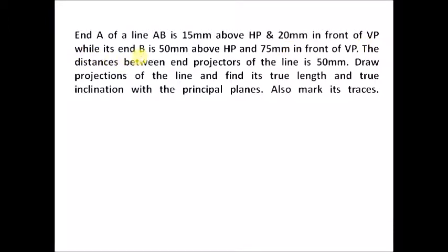Then further, end B is 50 mm above HP and 75 mm in front of VP. Same way, the point B dash is 50 mm above XY line and point B is 75 mm below XY line. In this way you have to mark it.